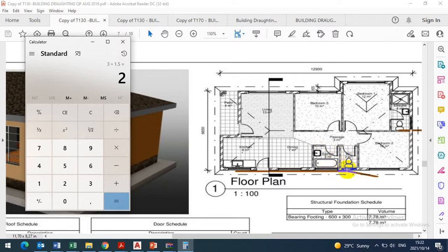Then you come to this other room, same. Let's say this room here is 1.5. So I'm going to add everything up before I choose the size of this room here. I'll add up 220, this brick wall, plus 110, plus this length for this toilet, plus the 110 brick wall, plus this length, maybe 2 meters, plus 110, plus this 2.6, 2,600.